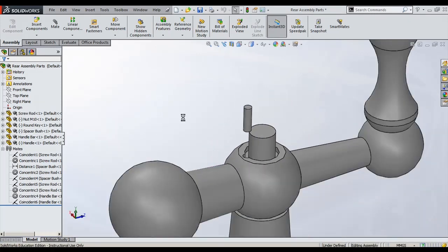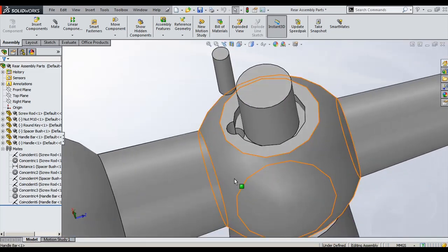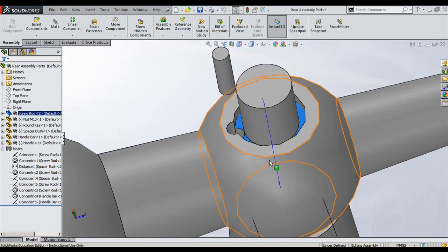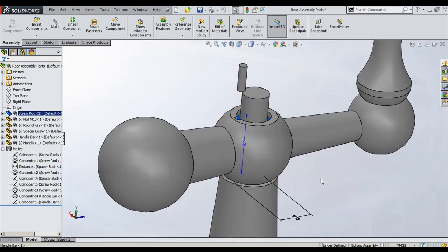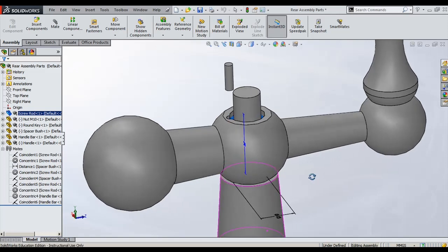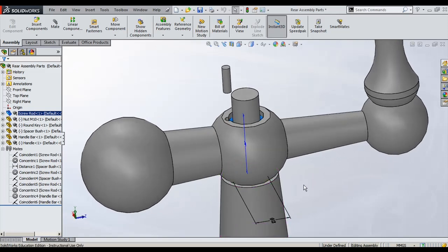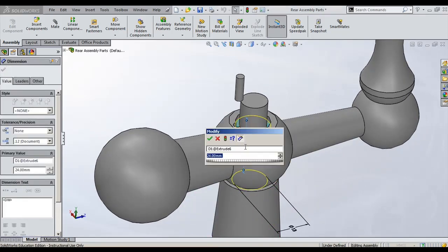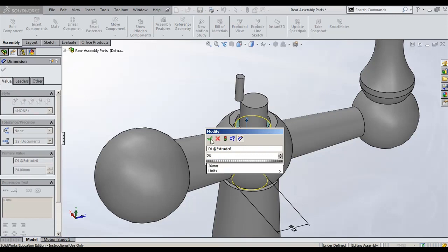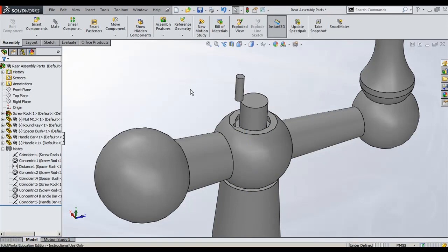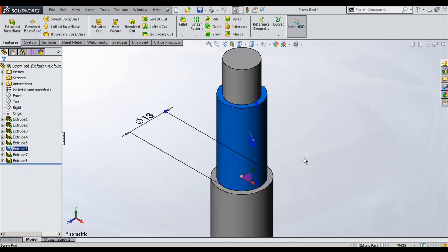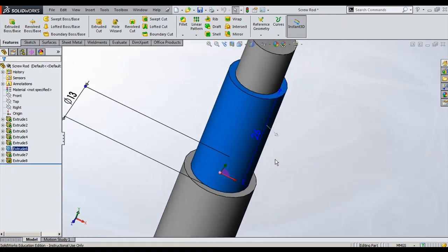So what we need to do is change the height of this revolve feature. So I will double click this area, which means now you are editing the screw rod directly in the assembly environment. You don't even need to open the part separately. I can double click this dimension and I will say 26, click OK and press Ctrl B. It will be updated. You can also open the part separately and view the changes updated here automatically. You can see the dimension is 26.